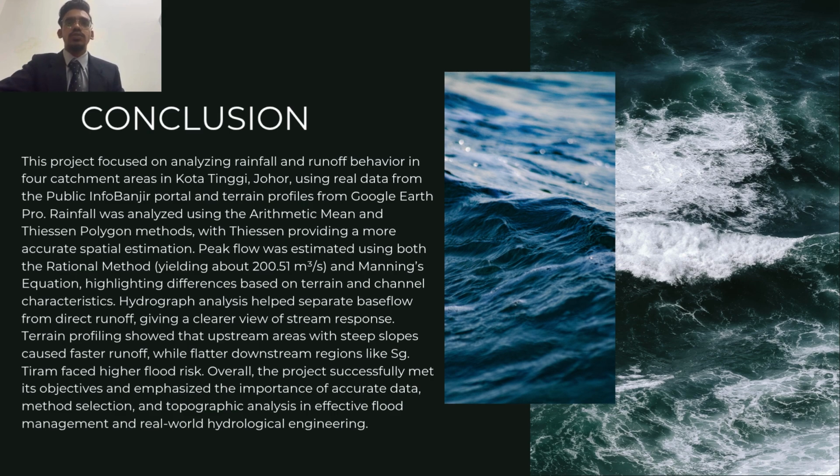Terrain profiling showed that upstream areas with steep slopes caused faster runoff, while flatter downstream regions like Sungai Tiram face higher flood risk. Overall, the project successfully met its objective and emphasized the importance of accurate data, method selection, and topographic analysis in effective flood management and real-world hydrologic engineering.